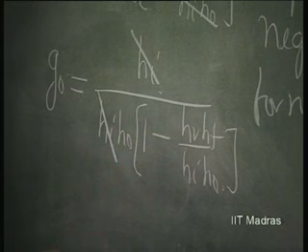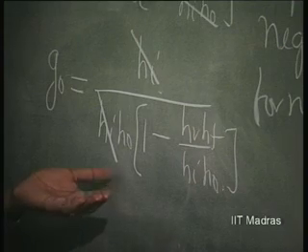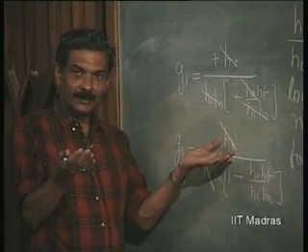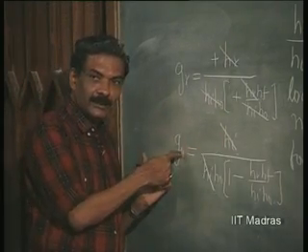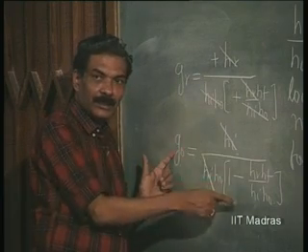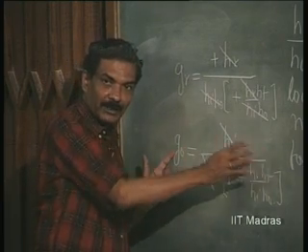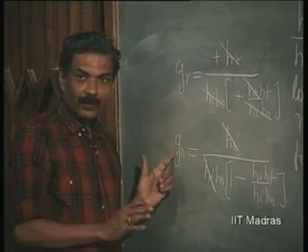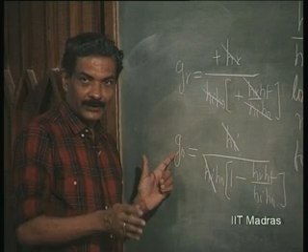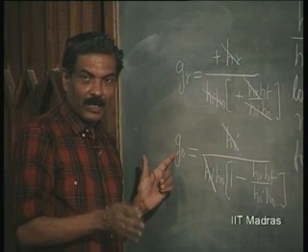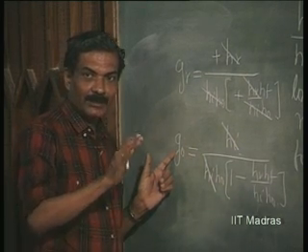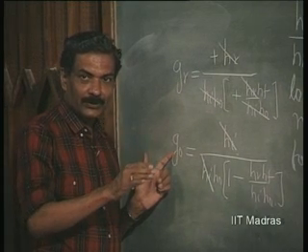It is going to get boosted up. The conductance is going to increase. That means the resistance, which is G naught, is going to decrease, goes towards 0. It becomes an ideal voltage controlled voltage source. The output impedance going towards 0 means it becomes a voltage source.